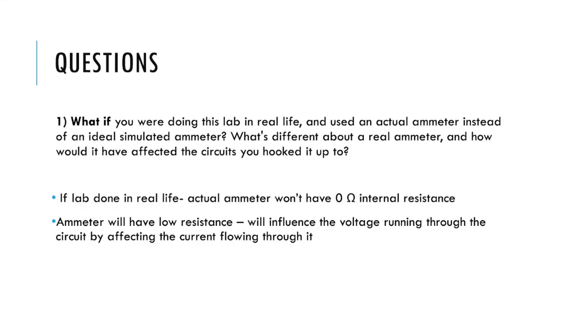So if we did the lab in real life, the actual ammeter won't have a 0 ohm internal resistance. However, it will have very low resistance, but it will still influence the voltage running through the circuit by affecting the current flowing through it. So our readings won't be the same.